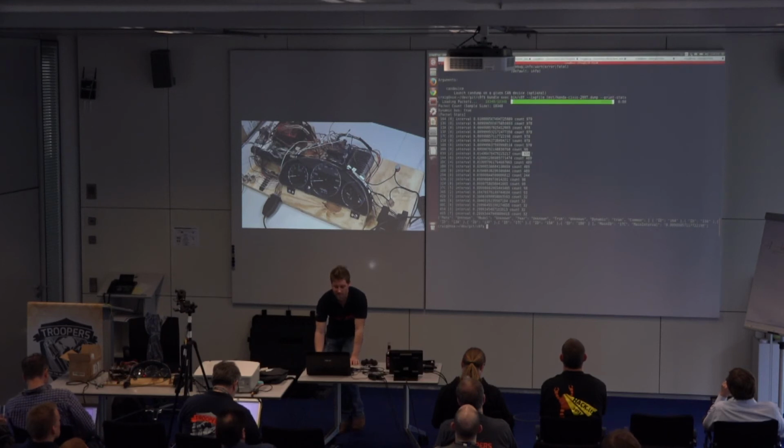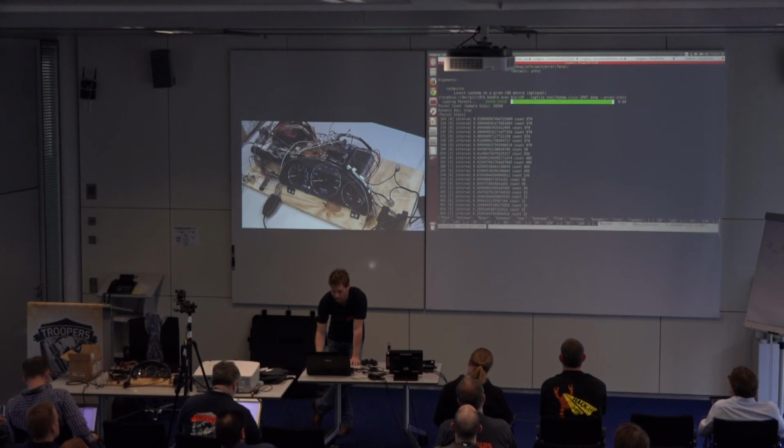And this fingerprint is really, really unique. So what you would do in your exploit code is, before you broadcast anything, you would basically just sniff. I would probably just go with this main ID one here. You would just listen for an arbitration ID of 17C, and you'd only have to listen for this long.